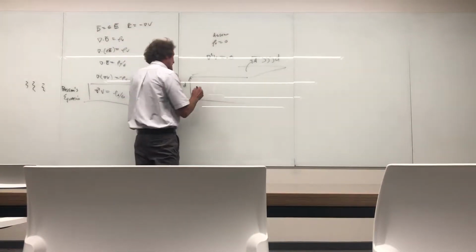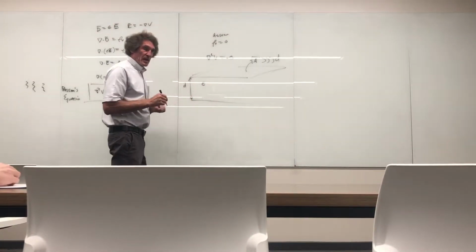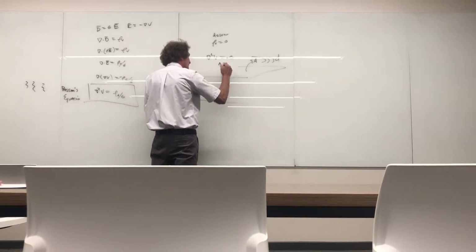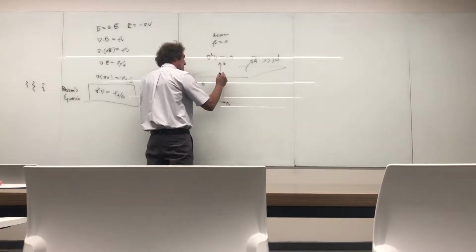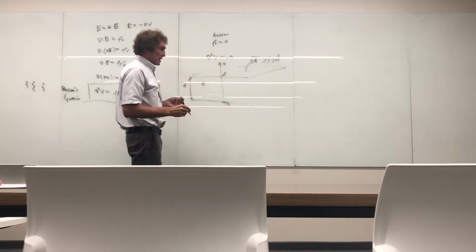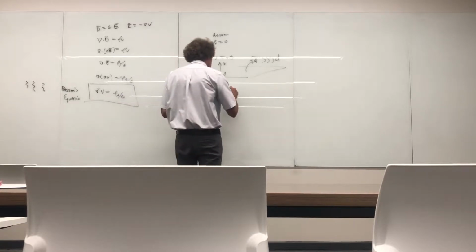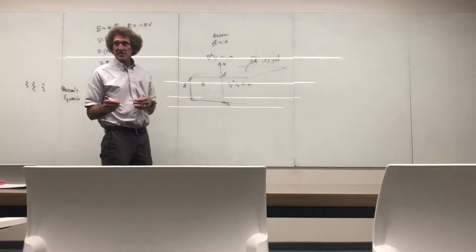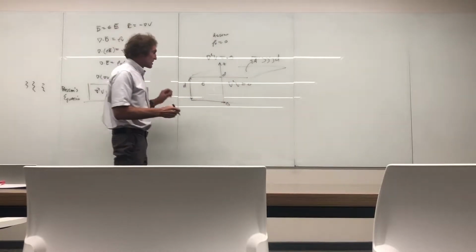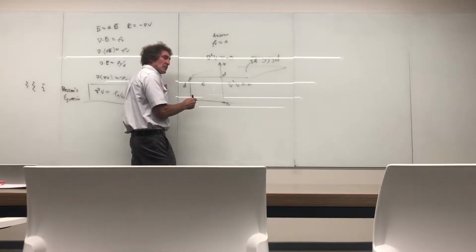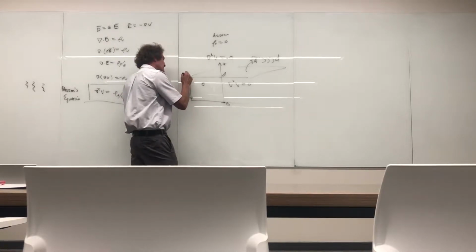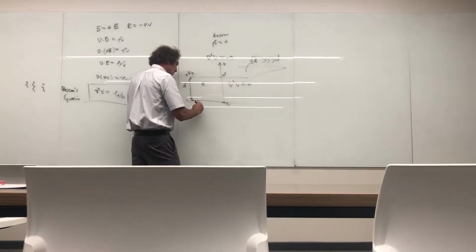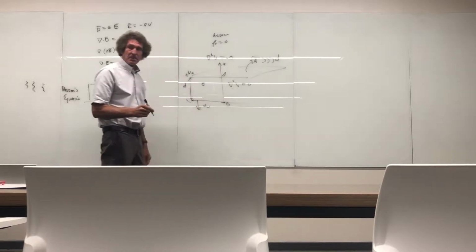In here, we're going to have a dielectric, a value epsilon. I'm going to make this the z-axis and make that 0. Therefore, this would be D. Now I'm going to solve the del squared of V equals 0 equation, and I'm going to get the capacitance per unit area in a second. I'm going to put a plus voltage here, V naught, and this lower plate I'll just ground at 0 volts. Okay? With me?